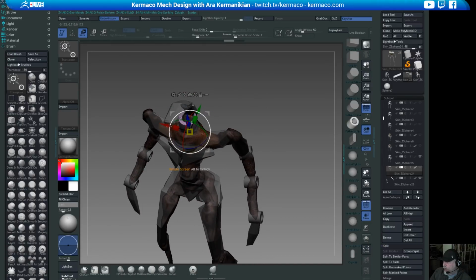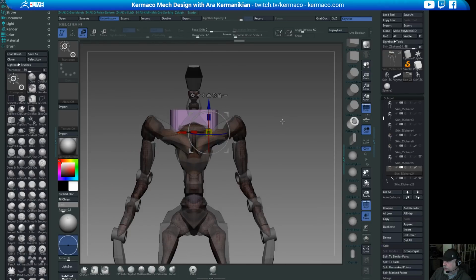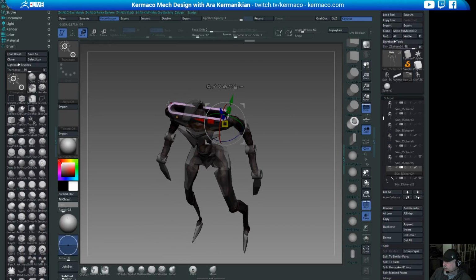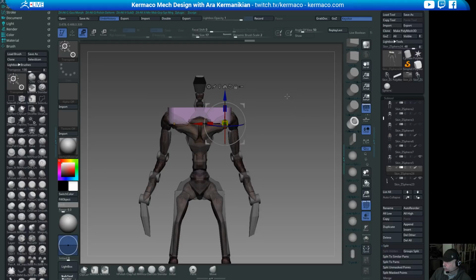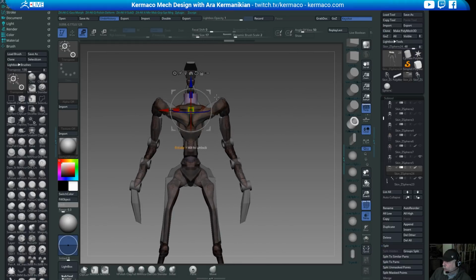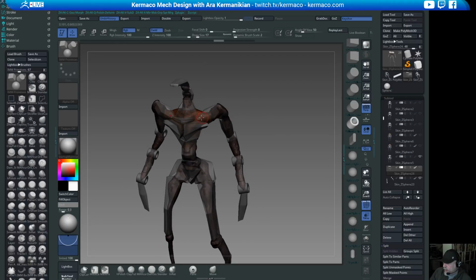Right, so if you're going to make a shape that looks like this, what you do is you basically turn symmetry on, X symmetry, place that object, and then as you move it, it will move it out this way. So this is how you can get this shape pretty quickly. So kind of a nifty little trick there. But here I don't want it to do that. I actually want two separate pieces, so I'm just going to go ahead and go back into draw mode and just draw out two separate pieces.